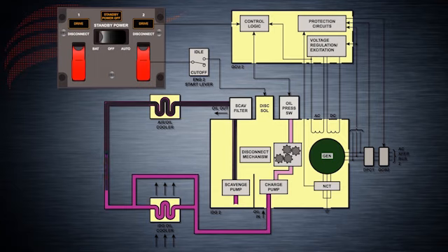Heat is exchanged between hot IDG oil and cool air from the engine fan. Oil is filtered, pressurized, and ducted towards the coolers at between 240 and 290 psi. If the filter were to get clogged, oil bypasses the filter and flows into the coolers.